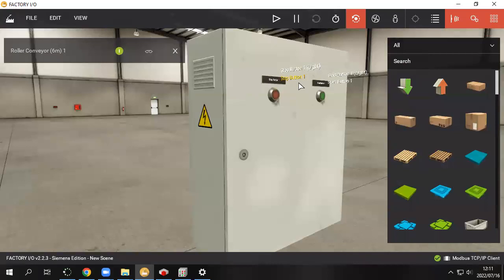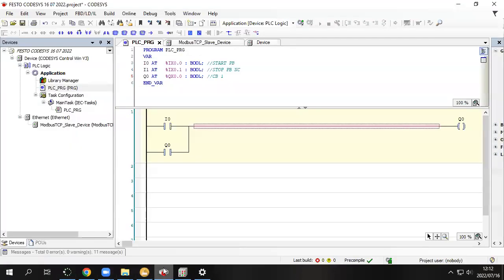It must connect unless it's engaged. So in high duty mode, it must always be connected. So it's normally closed. So you put it as a normally open contact in the code, so that when you press it, it can turn off. So this one is I1.